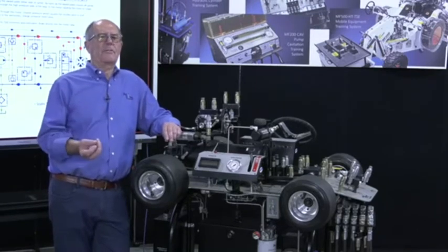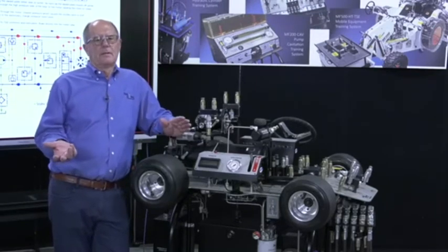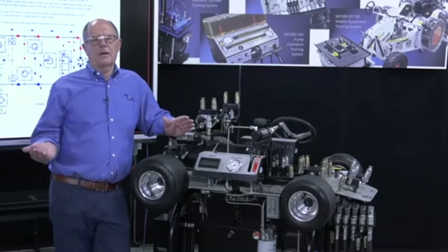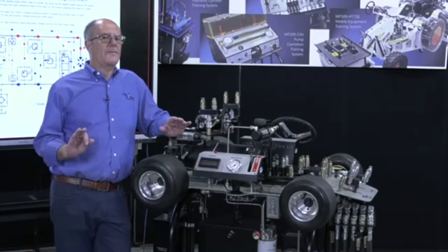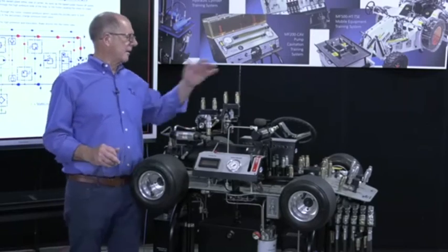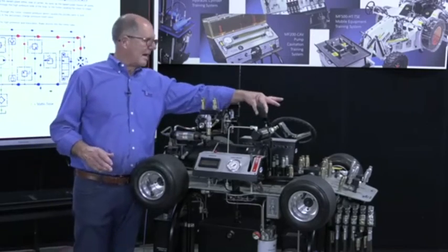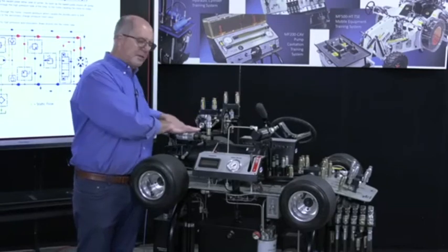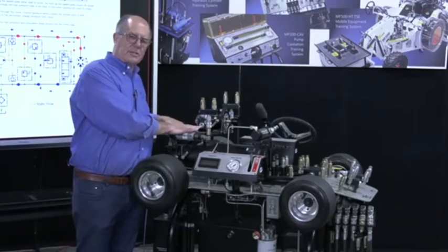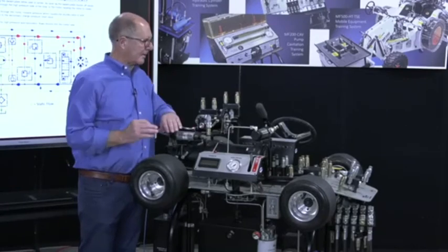In other words, we're looking for micro leaks. A pressure relief valve is a micro leak. You're not looking for 10 gallons a minute leaking from a relief valve. You're looking for fractional flow. And the only way to find fractional flow is with a micro leak. So this unit has a micro leak test pump on it to teach students how to test cross-port relief valves, test check valves, etc. in the circuit.